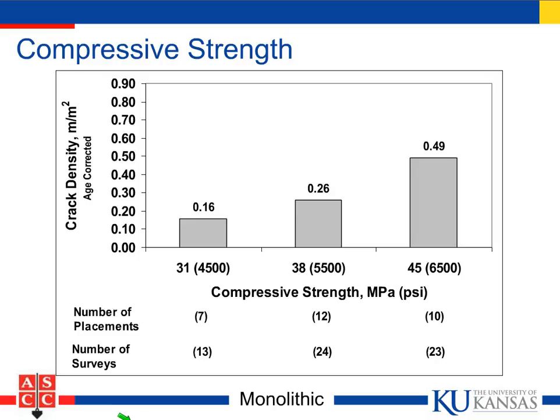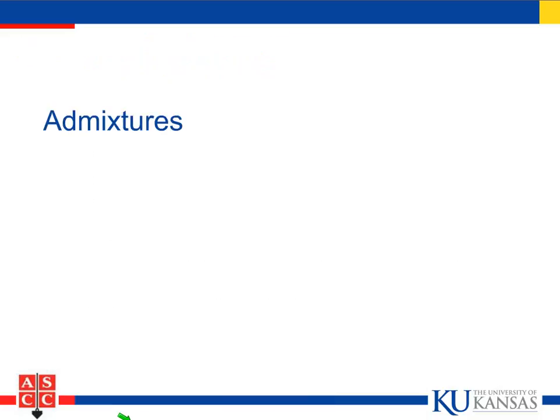Now, that's great on a high-rise building. We're using high strength concrete in columns. You don't want those columns to shorten up, and you want to limit how much they shorten up, so you want low creep. But when the concrete's being placed in tension, as it is in a bridge deck, creep is good because it helps relieve the stress. So that's why high strength concrete is not something that we're looking for if we want to have crack control on highly restrained concrete.